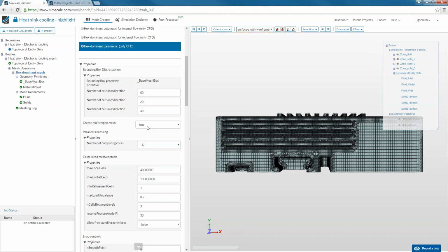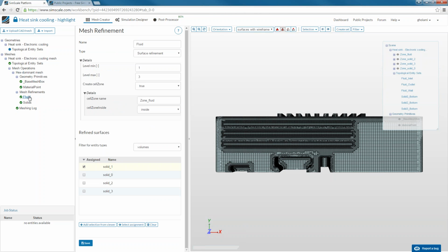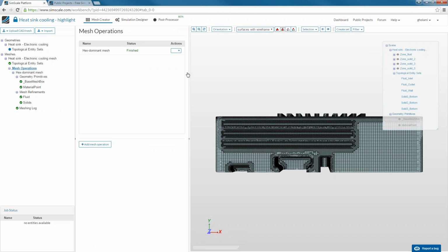One also very tiny hint, of course you can find these all in our documentation. If you want to refine your regions because their size is small, or for example for the fluid elements, you want to make sure to capture the thermal boundary layer when you're close to the surface of the solid. Therefore, you might want to define some additional refinements. This is done by creating a refinement as we did before. Maybe I'll also show that to you here.